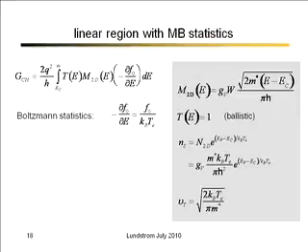Okay, now I have everything. Now I just have an integral that I can do, and it's not too difficult. Once you do that, you'll get a bunch of effective masses and kTs and things. But if you look carefully, it'll start to make some sense. Now, I'll remind you, I could compute the electron density just by integrating the Fermi function times the density of states. If you do that for a non-degenerate semiconductor, you'll get an expression that looks like this: something we call capital N_2D, which is called an effective density of states, times e to the Fermi level minus the bottom of the conduction band over kT.